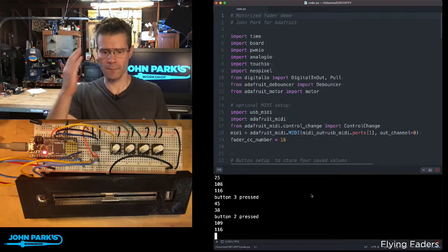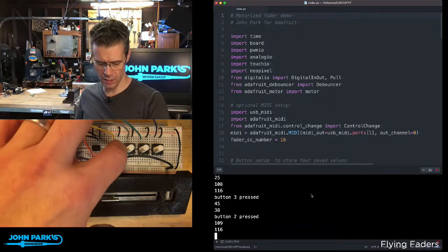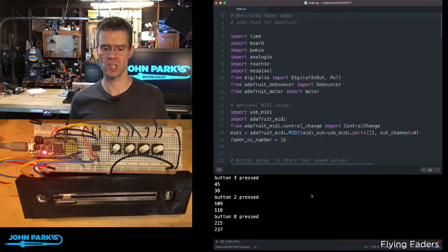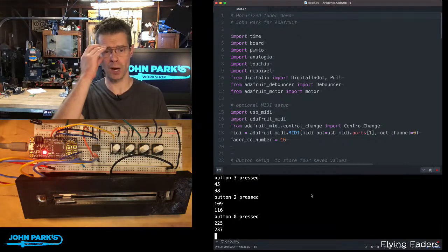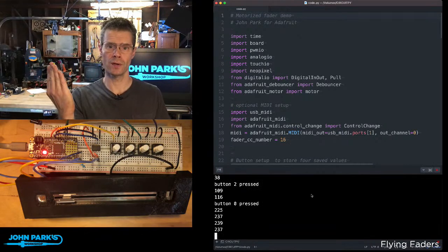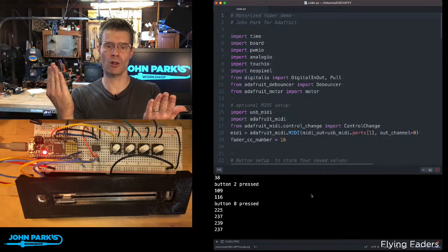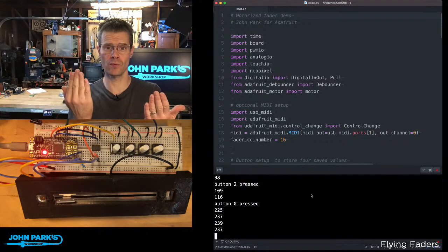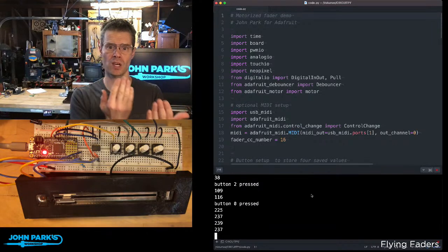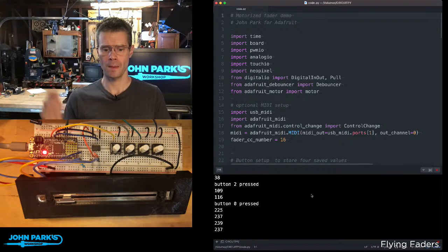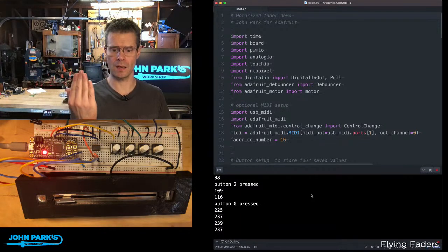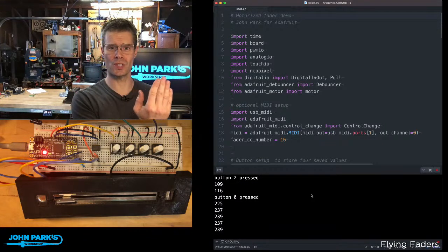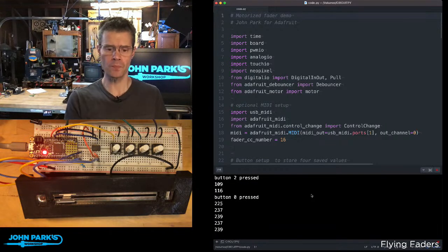And if you think about it, in these cases, when I'm telling it to just go to a position, this is a servo motor in the sense that there's this feedback loop of I tell it to move, and then I check the analog read of the slide potentiometer, because they're coupled to each other. And I tell the motor to move, then check, move, check, move, check, and it just keeps making a direct journey to the desired position, and then it stops when it gets there.